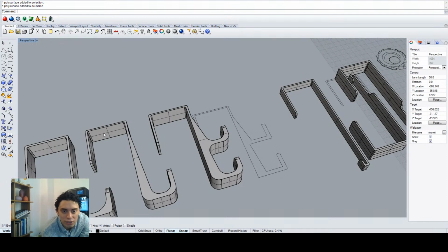The bigger this radius gets, the more likely it is that I will need some sort of scaffolding here for that material to be presented from the printer, right? So that the next layer over has a place to start. If I make this too big, then I need supports. If I need supports, I'm going to affect the print time, and ultimately it just takes more material. It's a very simple exercise, but I wanted to make it work as well and simplify it too. There are some things that I could have done differently, I think, thinking about it right now.